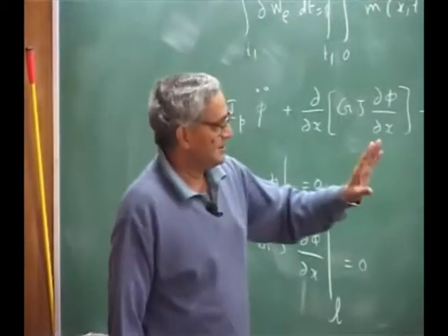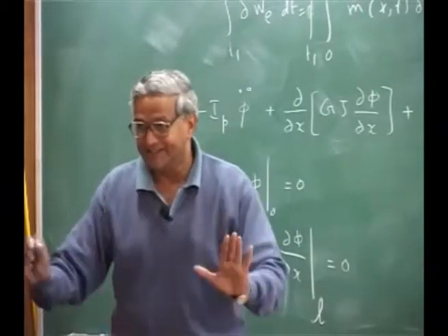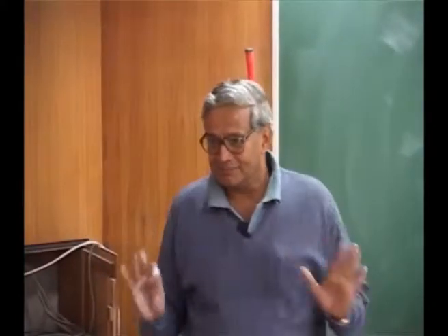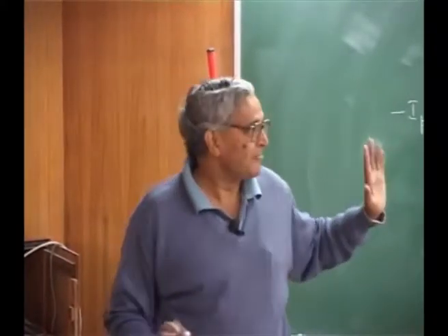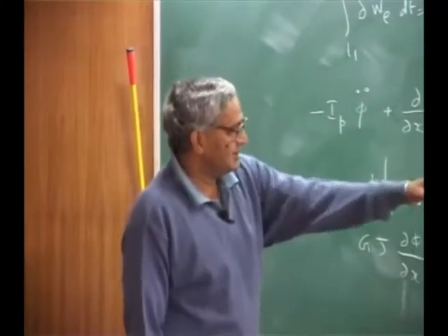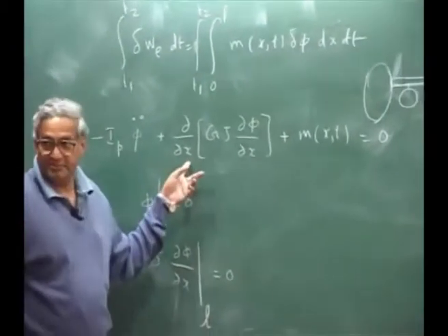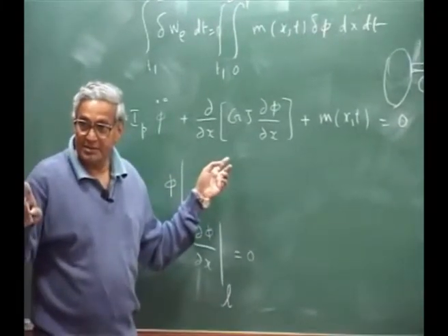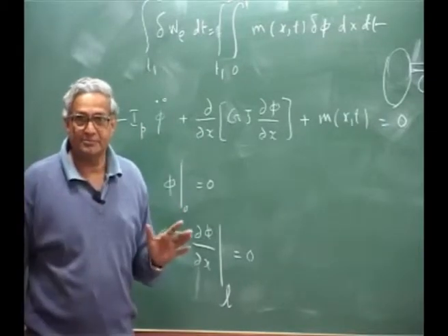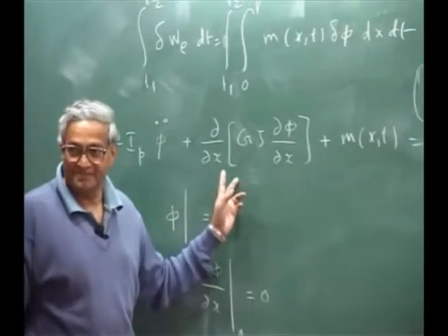Okay, we have taken only bending and torsion, because the wing can bend and the wing can twist. That is why we developed the bending-torsion problem. Now, something interesting between these sets of equations: look at the order of the space derivative. The time derivative is always inertia, the second derivative. The space derivative here is second order.